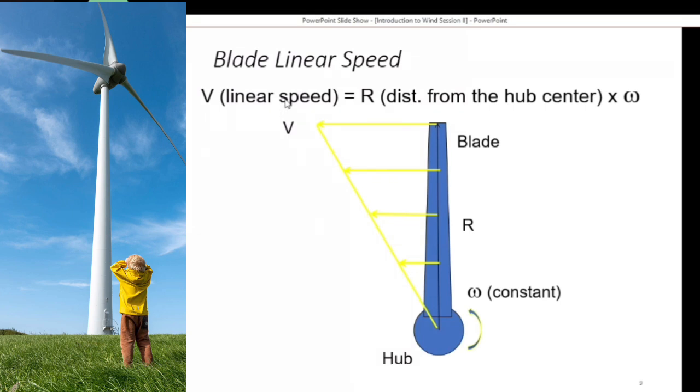Because you can see this linear speed is mainly based on the distance or the length of the blade. And last time I told you, the most common mistake students or others make is to forget that this is just the radius. The length of the blade is already the radius of the system. Because this hub is like the center, this will just create a circle, and this is itself the radius.